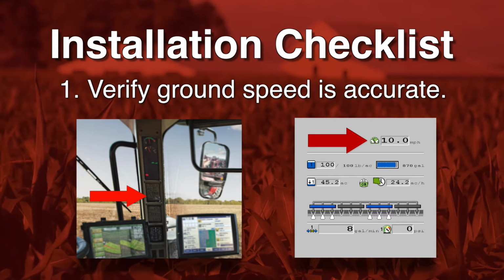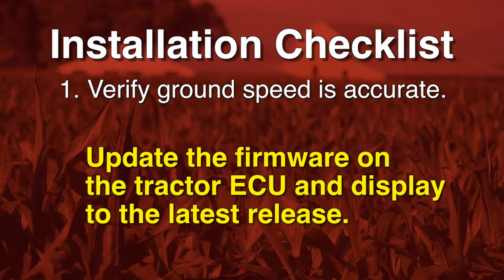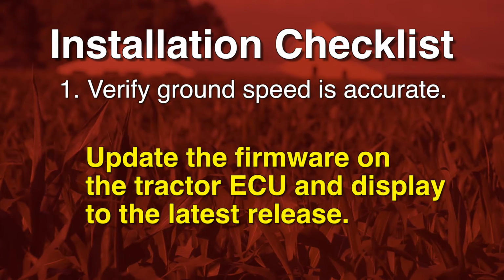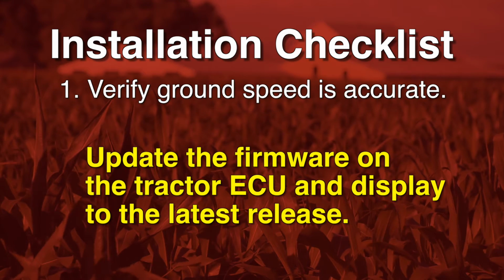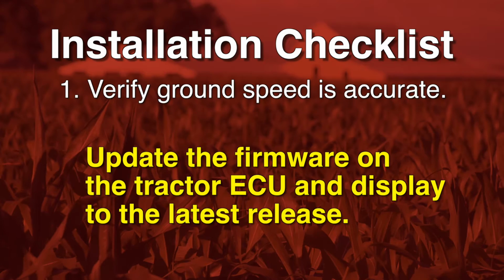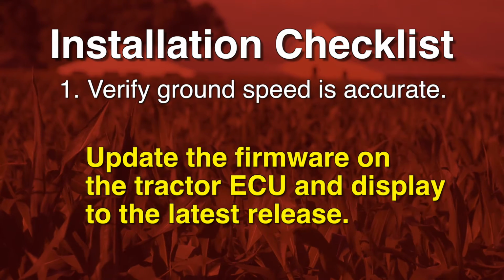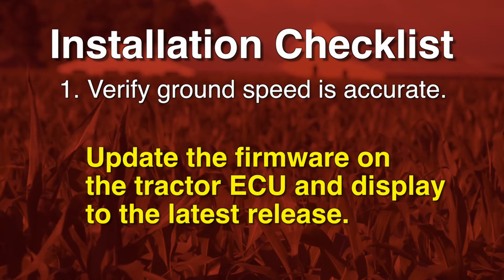There are two common sources for speed discrepancy. If the firmware on the tractor ECU and/or the display is not up to date, you may be getting an inaccurate speed reading. Once the ISOBUS system is installed, the tractor is now receiving speed from this source. Update the tractor ECU and the display firmware to the latest release to guarantee your ISOBUS system is correctly communicating the tractor speed.